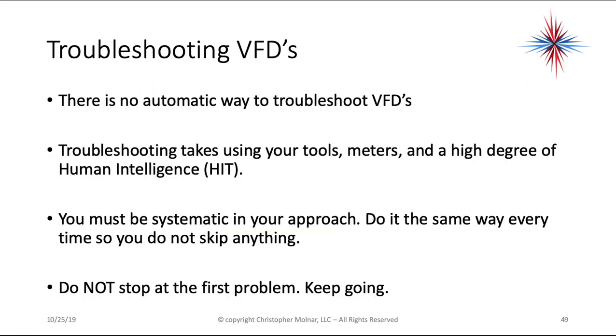There's no automatic way to troubleshoot VFDs. It takes your tools, your meters, and a high degree of human intelligence, otherwise known as HID. You must be systematic in your approach. You have to do it the same way every time so you don't skip anything. Do not ever stop at the first problem you notice. Keep going. If you notice a loose connection or burnt terminal or burnt capacitor, you have to keep going.